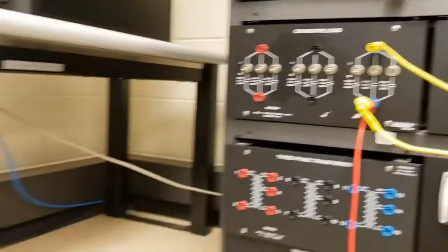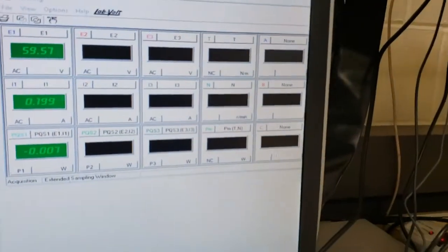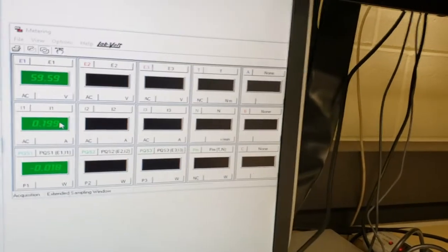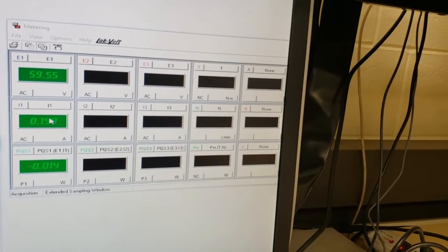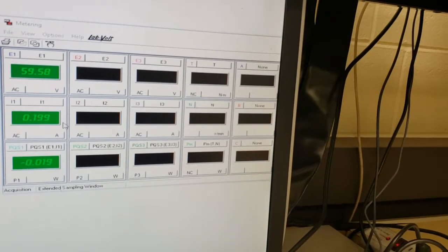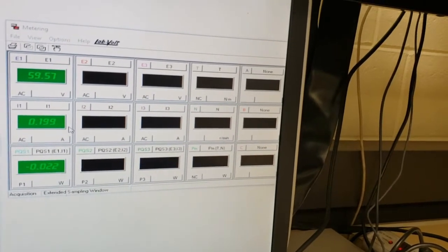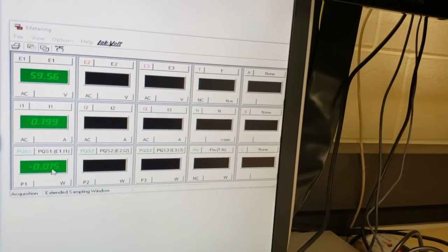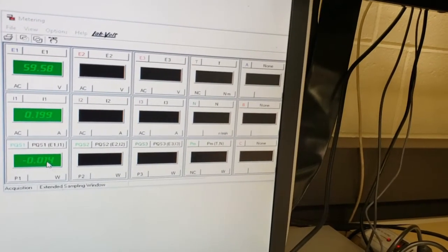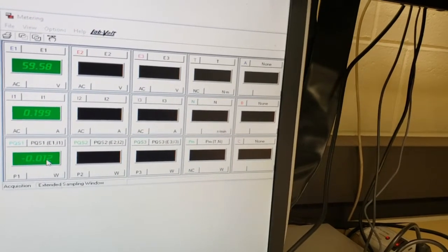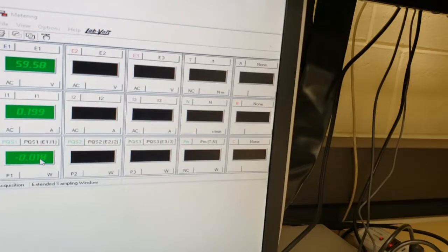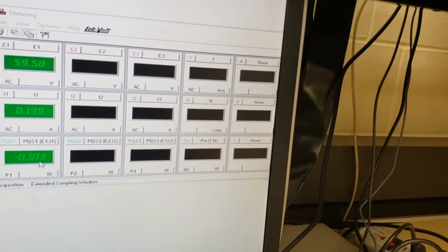If I turn it on, I'm just going to show the meter window first. So again, about 0.2 amps. In fact, this is very close to ideal here: 60 volts over the 300 ohms, minus j300 ohms of reactive impedance, gives 0.2 amps. There's very little real power being consumed, which makes sense. A capacitor would probably have less parasitic resistance than an inductor.